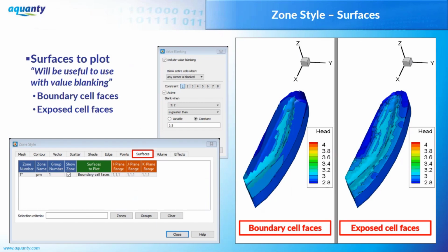Okay. You go through surfaces. Tecplot, when it loads the shape, it will load the edges only. So whatever is inside the model will be hollow, and it does that for ease. If it loads all the cells, it will be hard to rotate the figure and move it and so on. So the default surface that Tecplot shows is a boundary cell only. But on some occasions, it's not enough.